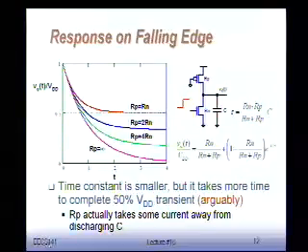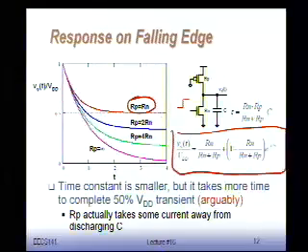Now, if you, however, look at the TPHL and you plot it for different values of the resistance. If I use, for instance, RP is equal to RN, you see that you pull down the output, and since they're the same, the V out is going to be 1/2 of VDD. Right? It's a resistor divider with both resistors the same, so it goes to 1/2. And then you have 2 times and so on and so forth, and you can easily describe this with this equation here. Now here's where the discussion comes.